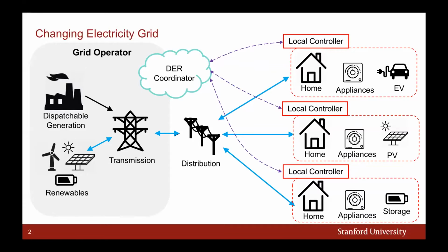A common feature of these local controllers would be to broadcast back to the coordinator often a feasibility range for control or some kind of forecast for power consumption in some time domain in the future. And so in this context, the appliance load model now is really critical to the local controller. If this house level forecast is going to be of any use, that power forecast has to be accurate.